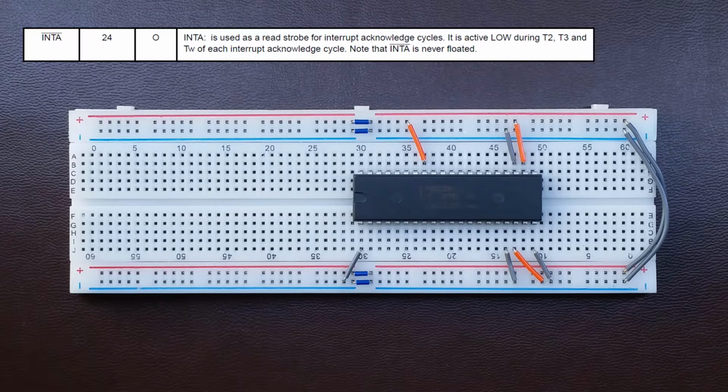Pin 24 in minimum mode is called INTA, interrupt acknowledge. It is an output, active low. Since we're not going to use interrupts for some time, let's simply ignore it for now.